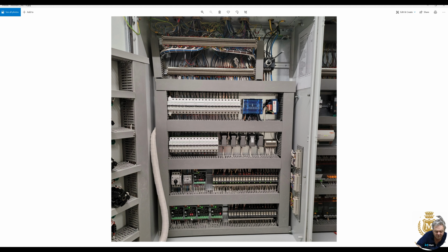So these input modules have an analog output up at the top here. Depending on the position or what's enabled, for example, this module's got 2 of them enabled, this module's got 1 of them enabled, this module's got 2 of them, you can see the 2 red lights on. That will send a numeric output back to the Trend. So one input into the Trend will actually give you 6 digital inputs.